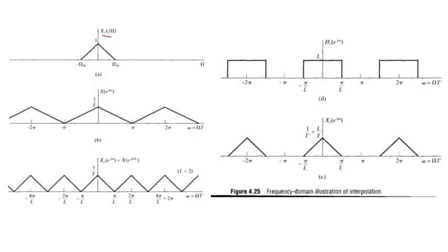So this is the spectrum of a band limited signal. This is the discrete Fourier transform. So the signal is converted from continuous to discrete, and we have skipped many steps here, and finally we get the omega axis. Now you can see that these points are touching. It means that the sampling frequency that we have used is equal to 2 times the maximum frequency. Next, we want to expand.